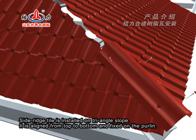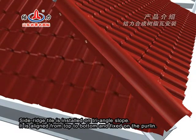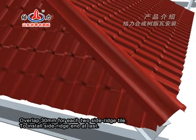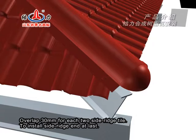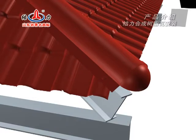Side ridge tile is installed on the triangle slope. It is aligned from top to bottom and fixed on the purlin. Overlap 30 mm for each two side ridge tiles. Install the side ridge end at last.